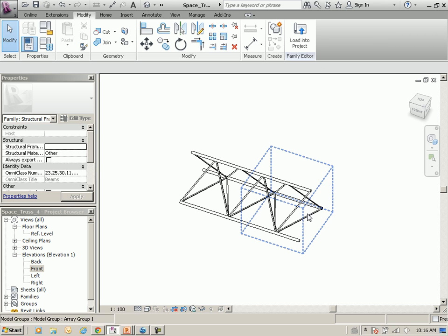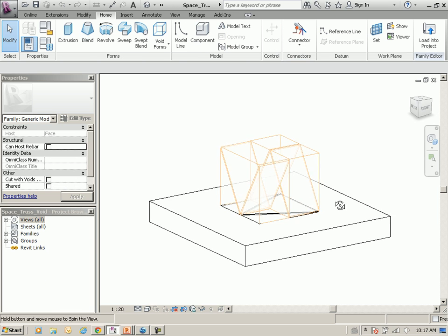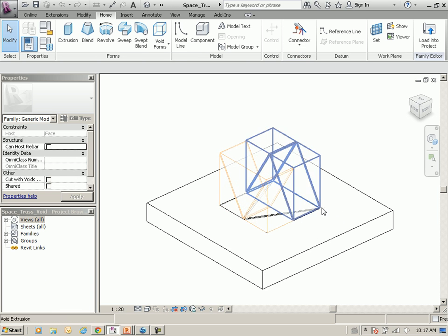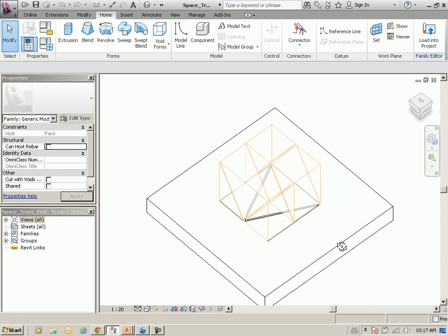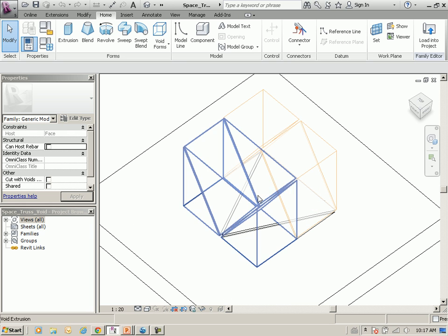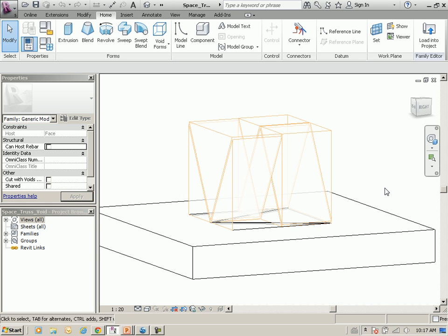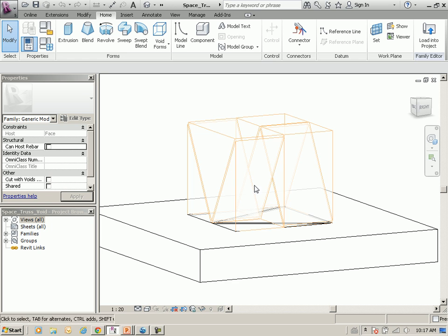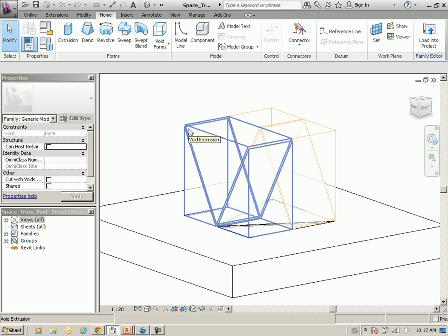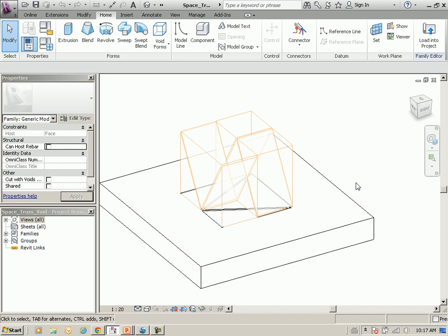Now, how did I make that little void family? Well, I'm going to just flip back over to that. Okay, so here's the example of the void family. So what it's doing is it's cutting this way, so from the sides and then from the bottom. And then it doesn't need to cut anything at the top because it's a triangle. So basically all of this is almost used like as a tool to cut. Anything left over will be solid.